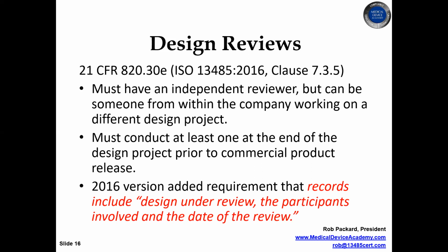You also are required to have an independent reviewer in design reviews. Because you're only required to have technically one design review, you could have just one independent reviewer available once, but my recommendation is to have an independent reviewer at each of the phase gates, and you don't have to have it be an employee. It would be perfect if you had two different design teams and they weren't working on each other's projects, and you could have some cross-pollination of ideas by having one team lead be the independent reviewer for the other team and vice versa. But if you're a small company, you're typically going to ask an outside consultant to help you facilitate the design review and make sure you do it properly and document it properly and sign off as your independent reviewer.